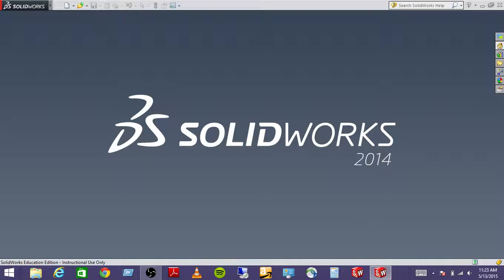So don't trust these parts to be structural components unless you've done a structural analysis on that component and you've determined that that material property can handle the loads that you're going to subject it to. So laser cutters are cool and they cut things out, but be careful where you use the pieces that you cut out. Okay.